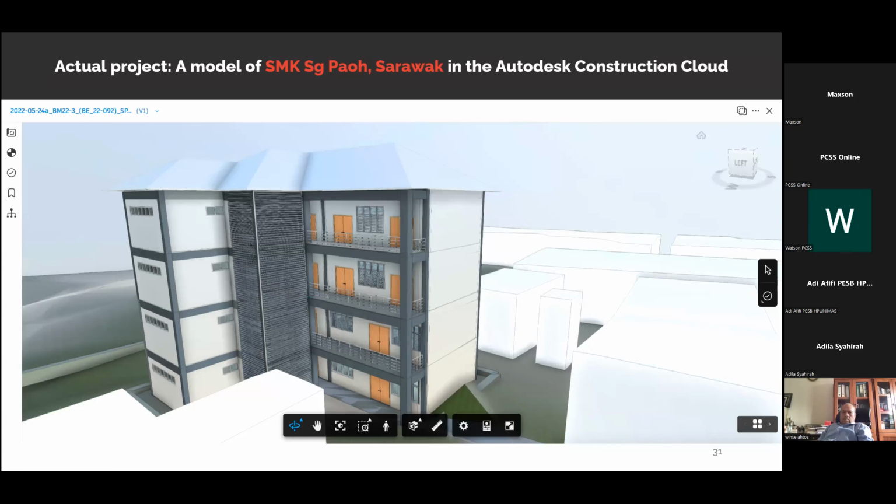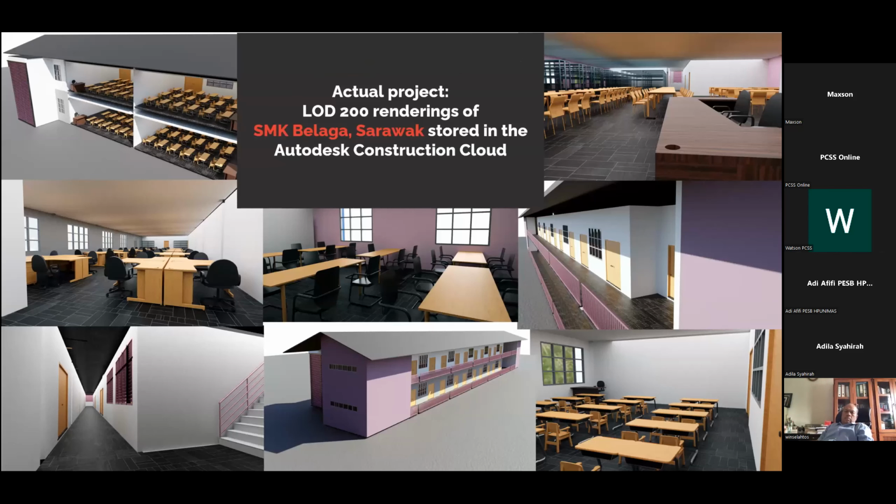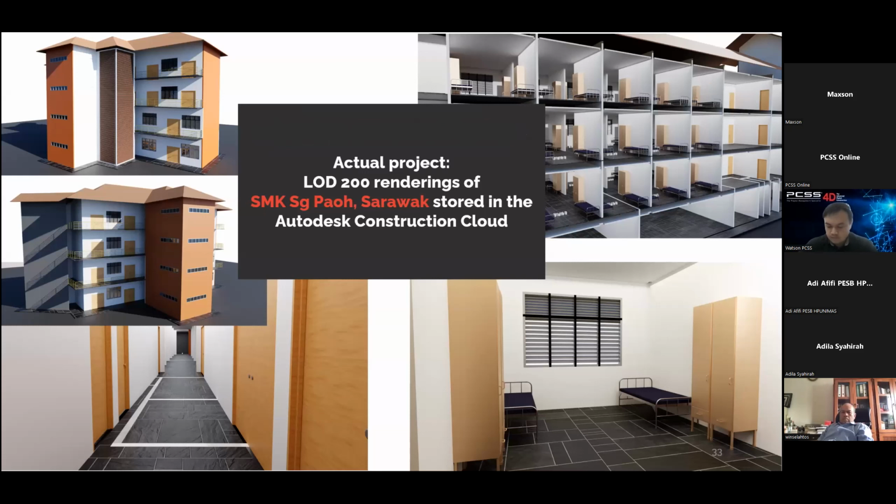And if you do BIM, of course, you have a 3D model. Even at the lowest level of development, you can produce many things. For example, using just LOD 200, we can create some simple visualization to express how it looks like a concept. Because we already do it using a BIM authoring tool, in this case Revit, we use some plugins like Enscape, which will produce live rendering, and then at least we can present some visualization for others to see.